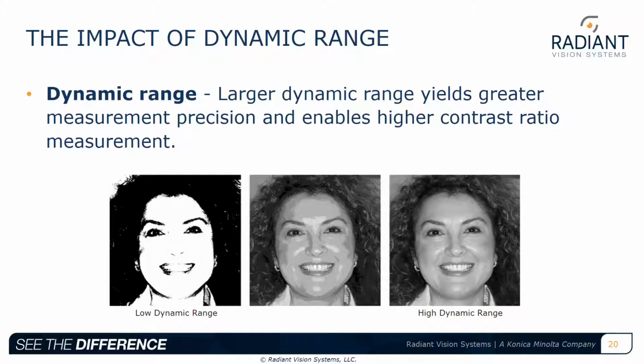This combined with high resolution is critical for fine detail measurement, where resolution is the number of pixels captured, and the dynamic range is the amount of meaningful variation between the pixels. With a high resolution, broad dynamic range camera, machines can perform inspection with even better acuity than human vision, easily detecting whether cables are routed below or on top of cable guides, or if a black screw is missing from a black surface.